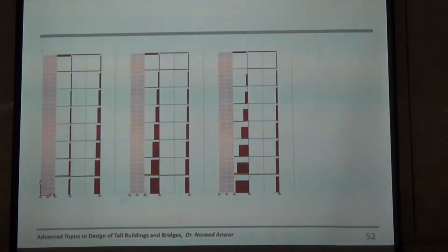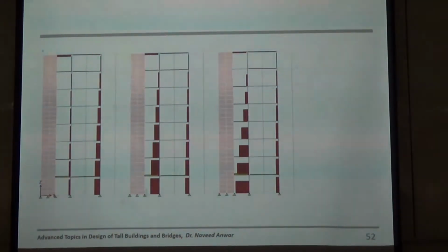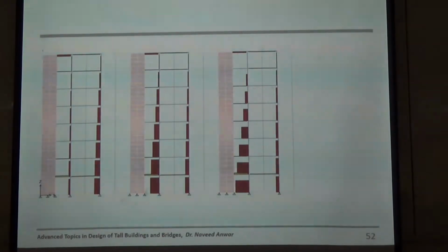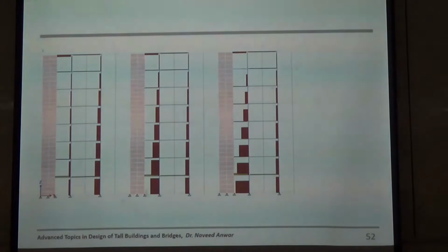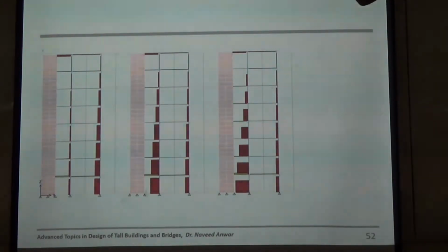And the link beam strength can be controlled to provide just enough, not too much. We can provide the reinforcement in such a way that after a certain bending moment, it will yield. So it's a controlled device. It doesn't have infinite stiffness, it has yielding. For some load it will continue to be stiff, but after some load, it will yield and bend.